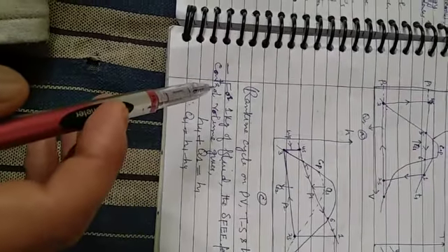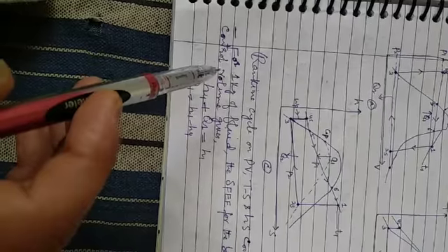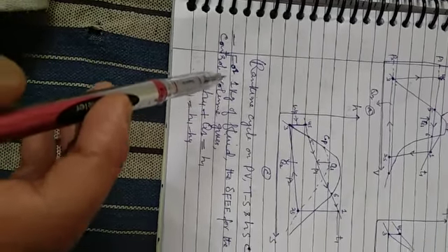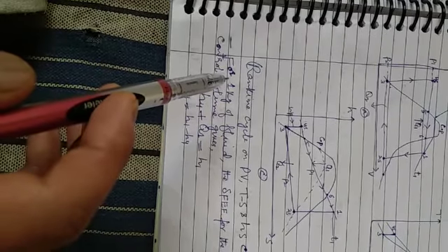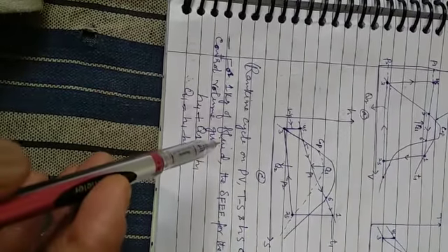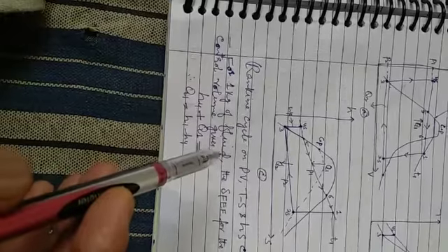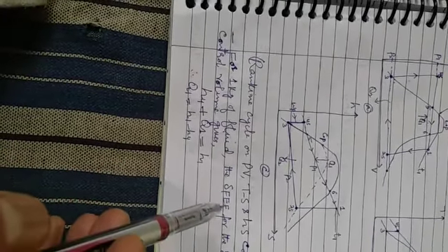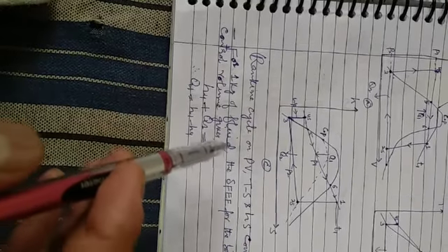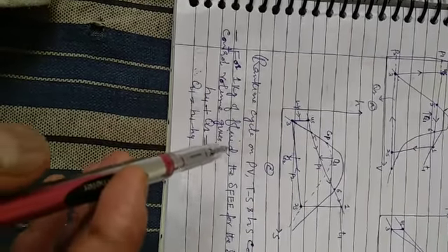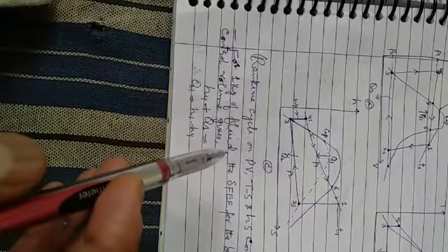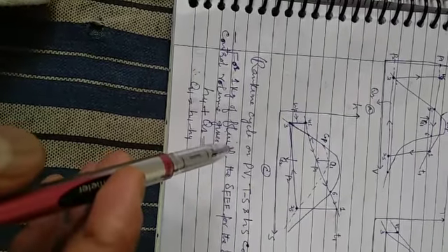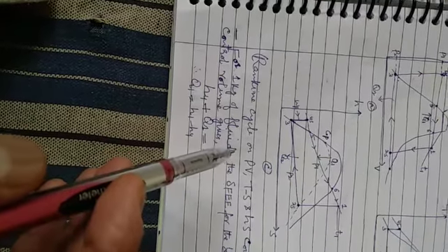For calculating the work done and the thermal efficiency of the Rankine cycle, you have to suppose that 1 kg of water enters the cycle, and you have to apply steady flow energy equations for the boiler as well as for all the sections. You have to apply the steady flow equation for all the processes, that is, energy equations used for flow processes.